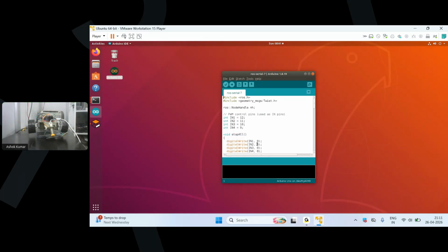And topics are what? Topics are basically the concerns, the issues which we want to identify or to run. For example, when the Python code wants to know the distance, the concern of the topic is distance, where Arduino is the publisher and the Python code is the subscriber. And when we are sending the commands of WASD, at that time the Python code is a publisher and the Arduino board is a subscriber. It's like suppose there are two YouTube channels, channel A and channel B.